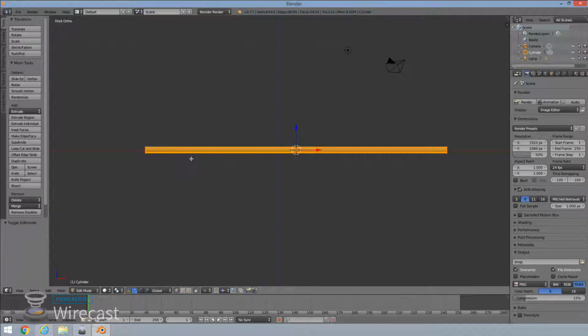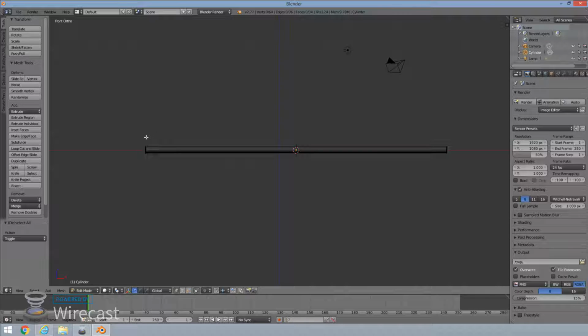Alright, good. Let's go into edit mode. Make sure you have your button selected here so you can select all your vertices when you're making a selection. This is your limit selection to visible, clip with depth buffer. The way it is right now, if I select a set of vertices like so, it will only select the front face, or what's facing me in this case. The rear section, none of that's selected. So I don't want that. I want to select the rear portion as well. Very important button. It will save you a lot of work.